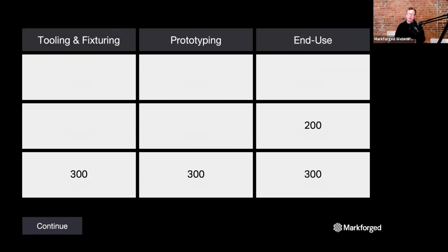One person did bring up a good comment about thermal expansion issues with plastic in metrology. So in general, because of that reinforcement and because of the onyx material, the parts are very dimensionally stable. So you're not going to see that much expansion or anything like that, because the carbon fiber, both in the onyx and in the reinforcement, will essentially ensure that the part stays dimensionally constant.